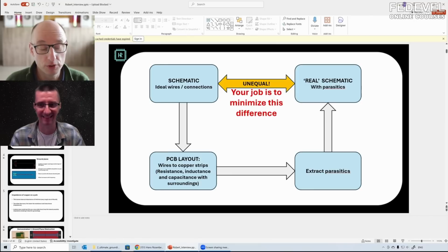If you only have a microcontroller, your functionality will not be hurt, but you may be transmitting quite a lot of interference. And if you want to sell a product, then you may cross certain EMI boundaries. So if you want to qualify your product, then you could have problems, and they can be expensive because then you have to redesign your board. If you already know what the problem is and what you have to do about it, you know.